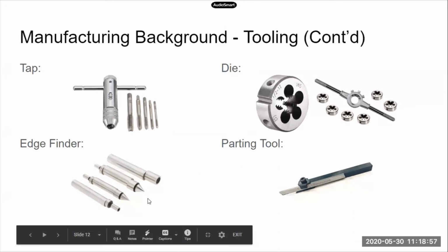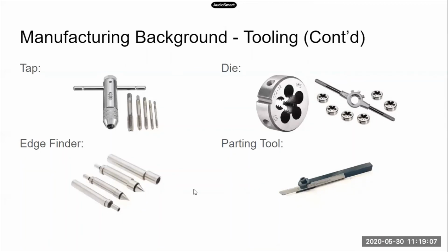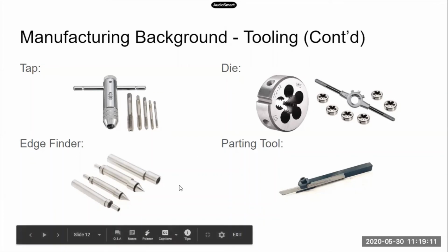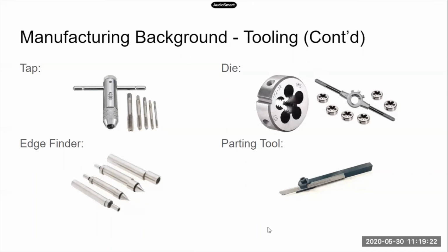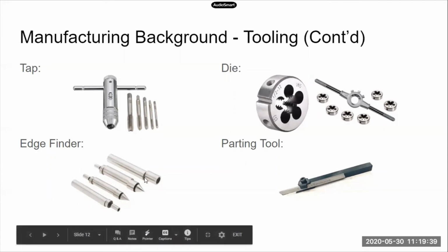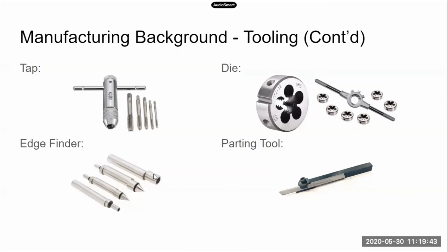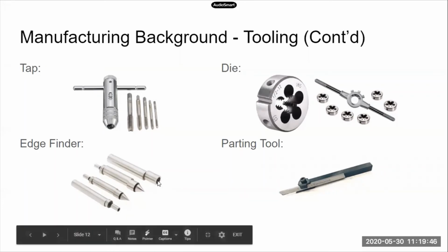And then, as I said, the edge finders tell you where the edge of the material is. This part here spins really fast, and the centripetal force is keeping it spinning around. This is tied in with a little cord right here that you can't really see. So imagine this part spinning around the outside very fast. You can see the cylinder here, and then a wider cylinder from the other part moving around. As you get closer to the part, it will start to look linear, and then you just do the tiniest increments until it throws it off center, and that's where you mark the origin, and of course offset from that by whatever amount this radius is here. Otherwise you'll be measuring from the outside of this rather than from the center.